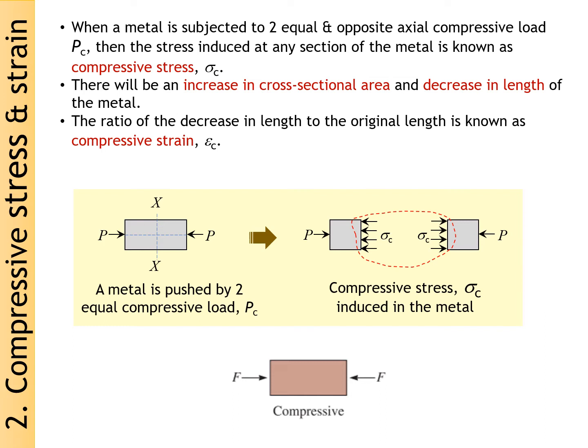A compression test is conducted in a manner similar to the tensile test, except that the force is compressive, towards the member, and the specimen contracts along the direction of the stress. The equations similar to tension are utilized to compute the compressive stress and also the strain.